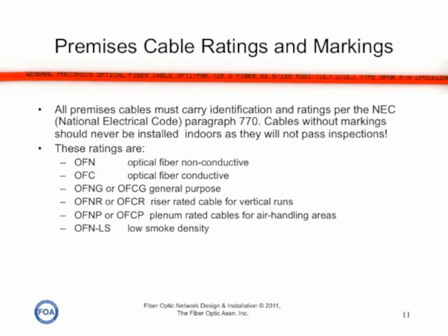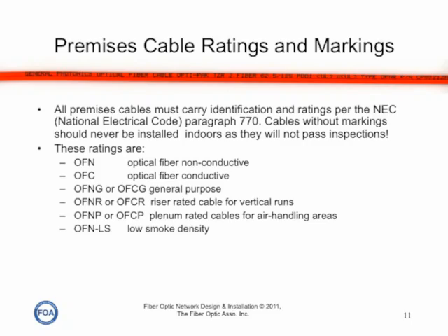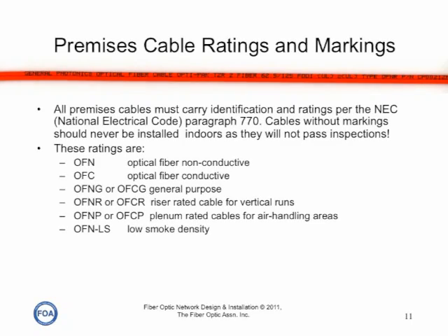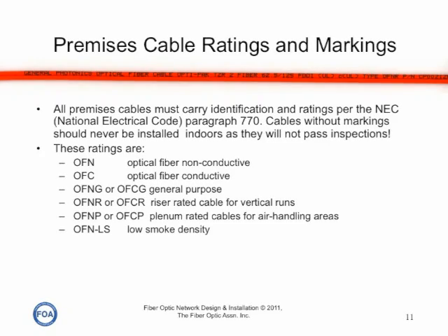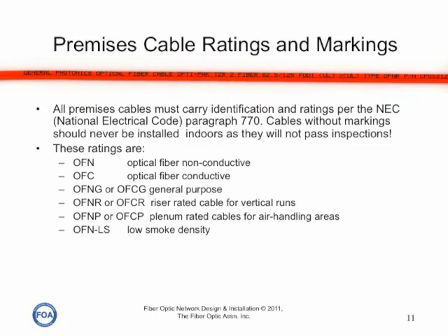All premises cables must carry identification and ratings. In the United States, it's per the National Electric Code, or in Canada, the CEC. Cables without marking should never be installed indoors, as they will not pass inspection. And of course, since they may be flammable, they're not safe.